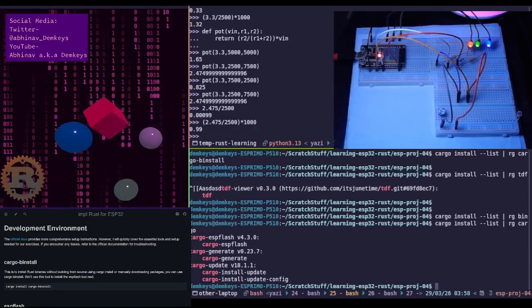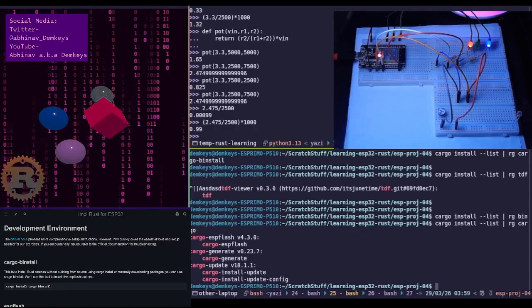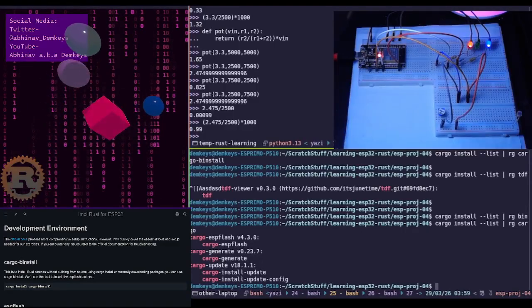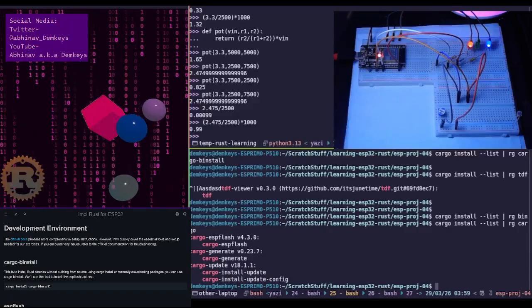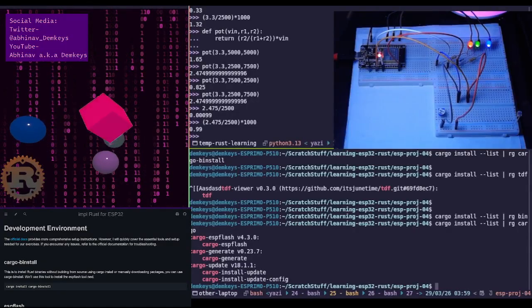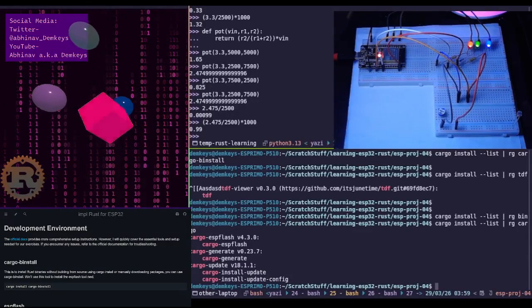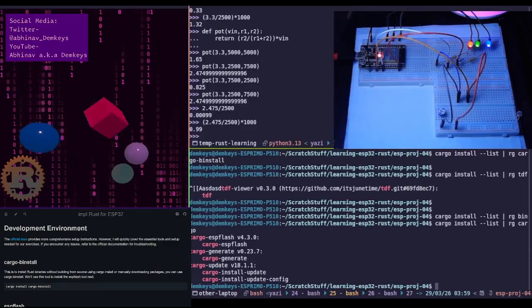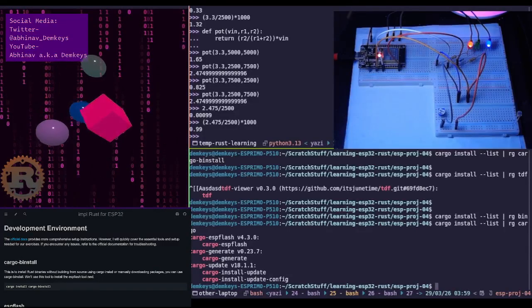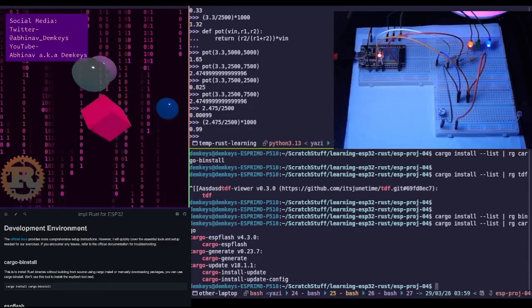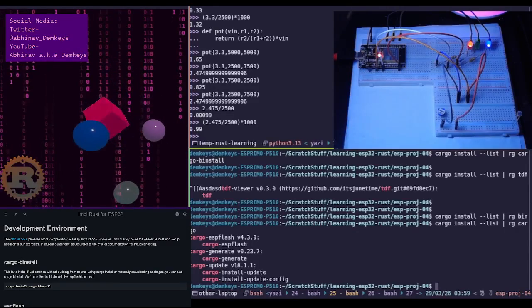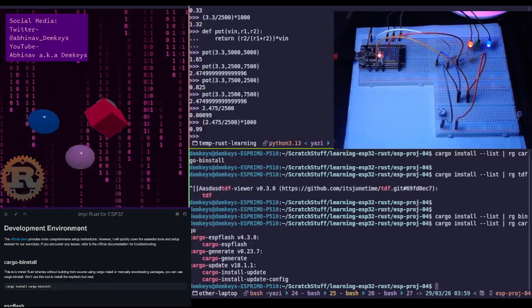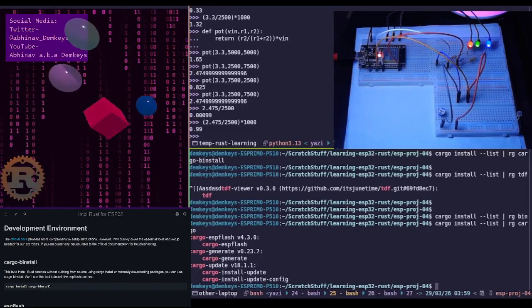Oh, okay. So Darlington is between 50 milliamps and 150 milliamps, so that's not a whole lot. But the power optocouplers can handle anywhere between 1 amp to over 100 amps. That's crazy. The use cases are directly switching AC mains power, heaters or industrial, so this is industrial level stuff.